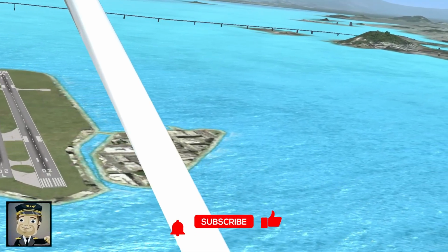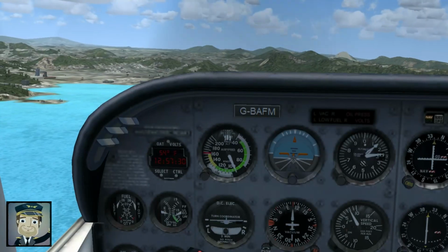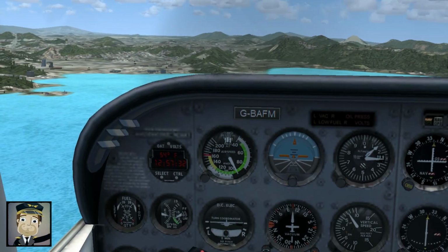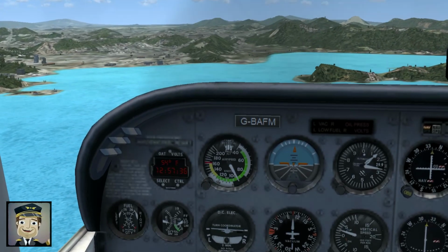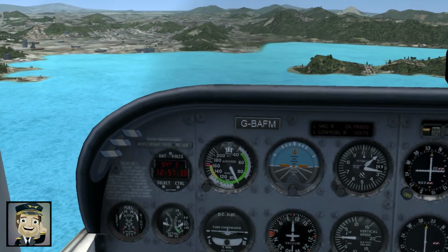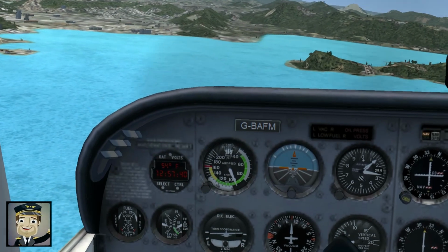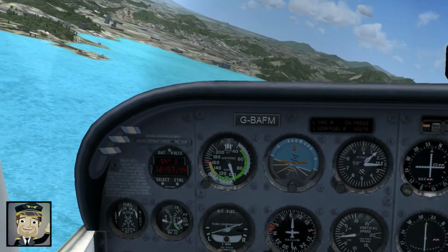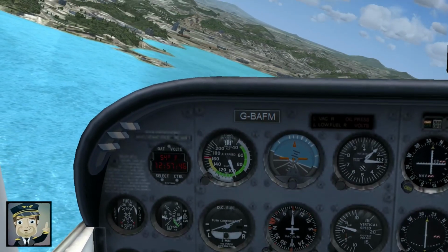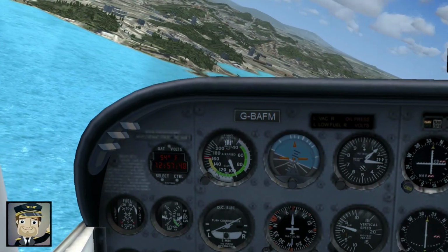The crosswind leg is critical because the airplane is still relatively low to the ground but already distancing itself from the runway environment. Vigilance is key. Radio communication, visual scanning, and maintaining a stable climb must work together. During this leg, pilots typically aim to reach traffic pattern altitude, stabilizing the aircraft before the next turn.